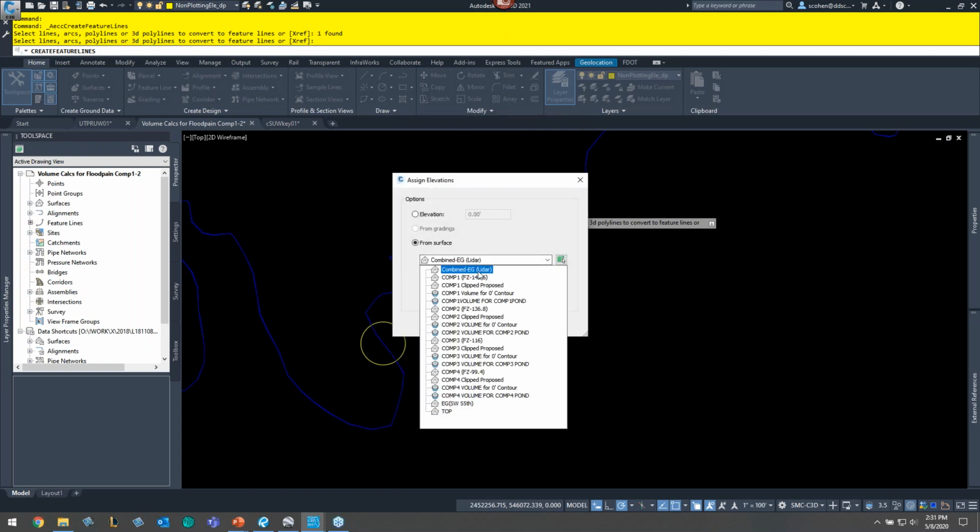And then again, I have existing ground, but I also have LiDAR. Again, you may or may not have this. What you can do, this is definitely a possibility, you can use Model Builder in InfraWorks. As long as you have the AEC collection, you'll have access to this. You can get the USGS contours, just basically do an area of your project, just do a rectangle, and then bring that surface in from InfraWorks. Okay, that's a little trick.